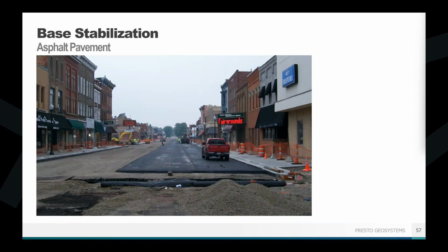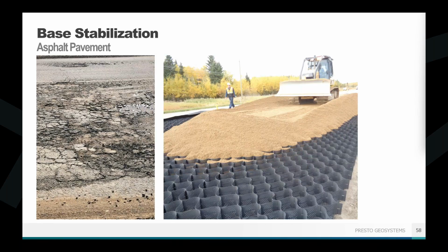It's going to be your standard asphalt equipment, asphalt paving installation. None of that part of it's changed. So you don't need any specialty equipment, specialty training for your contractors, anything like that. Once the GEOWEB panels are down and in the ground, you treat it like it's your standard subgrade and you're able to go.